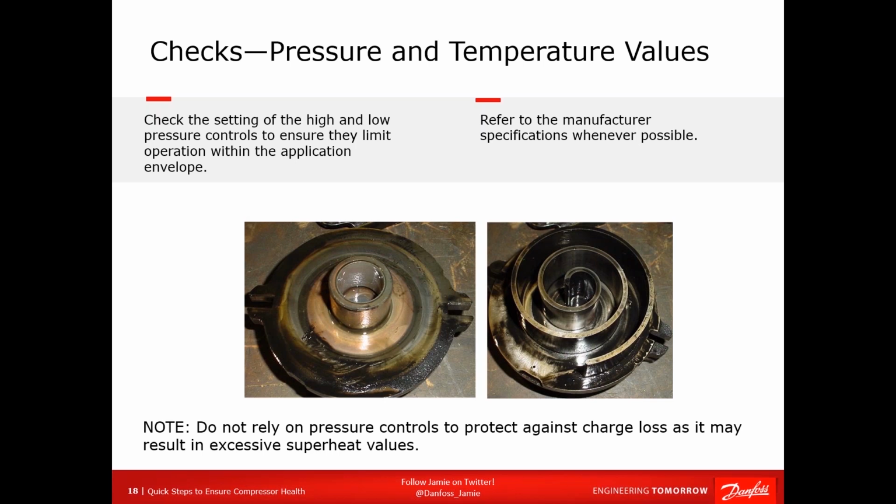So if you replace a compressor, one of the key things you need to do is to make sure the system is absolutely leak-free. Because remember, that compressor failed for a reason. Unless the system is 25 years old, it failed before its time. You need to find out why. Otherwise, there's a good chance that new compressor you dump in there is going to have the same fate in a much shorter period of time than you'd like.